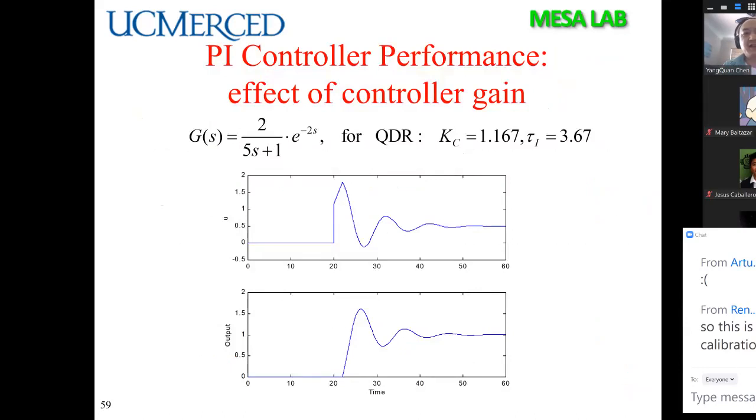So we have the first order plus delay, K, T, L. What is this one? L divided by T is 0.4, which is less than 0.5, so you should use PI. I told you, it's called quarter damping ratio. Basically you check here: 0.5 is the steady value.